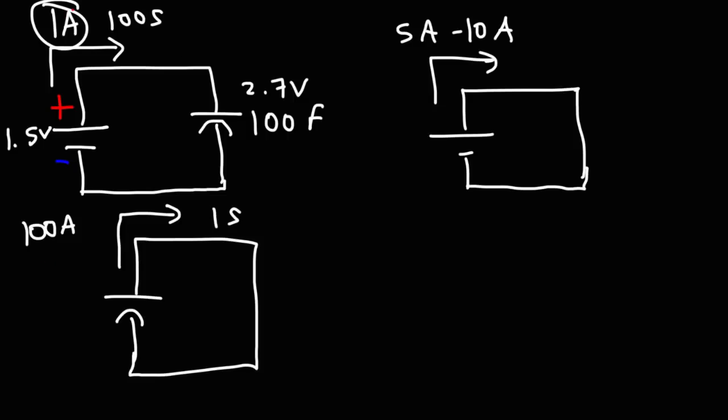So in this example, it took a long time to charge this capacitor. So we got a small amount of current being applied to this capacitor over a long time period. But when the capacitor discharges its energy, it can discharge a very large current for a short period of time. Energy is not created in this process, it's simply stored. But notice how the capacitor can increase the current by decreasing the time in which that current is active. So capacitors can be used to discharge very large amounts of current, which can be useful in certain applications.